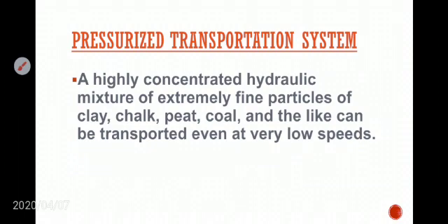And in the pressurized transportation system, a highly concentrated hydraulic mixture of extremely fine particles of clay, chalk, peat, coal and the like can be transported even at very low speeds. Here what I mean to say is, sometimes when we do hydraulic mining to transport a very soft material like chalk or clay, we know that they can completely get dissolved into the water.